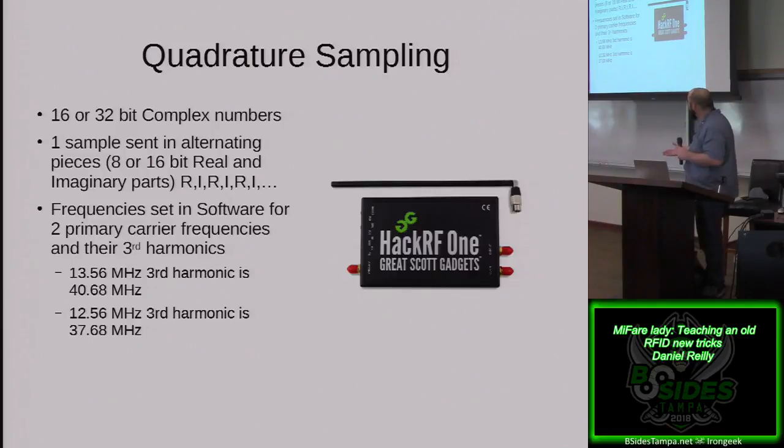Luckily in HackRF you can do that in software, but it starts to get really laggy. So I recommend using 2 radios, and I actually picked up an RTL-SDR as my second radio. Now, the HackRF can sample at about 20 million samples per second, or 20 megahertz, and the RTL-SDR can only do about 2 million.